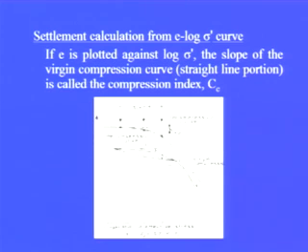So only elastic compression or the elastic rebound we obtain here when we unload it, and after unloading it we can again reload by the same intensity of load, and then we plot the e-log sigma bar curve. You will find that after this particular pressure has reached, at the pressure more than this, the nature of the curve merges with the nature as if the soil has not been unloaded.